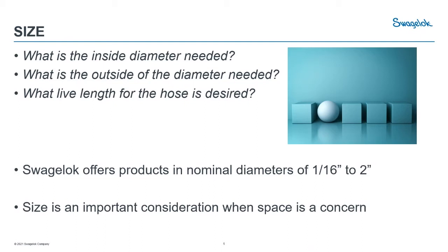So say you need to match tubing to 1/2 inch parts, you would select a 1/2 inch OD for your tubing. Another thing to remember is the size of the tubing you need is always going to relate back to the flow in the system. Flow is what drives the size tubing you need and drives much of the selection of any product we offer. So if you're questioning your choice when you're selecting your product, know that we're here to help and we're happy to do so.